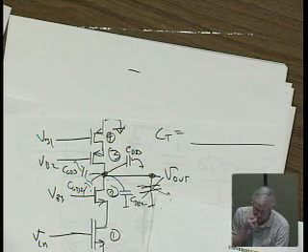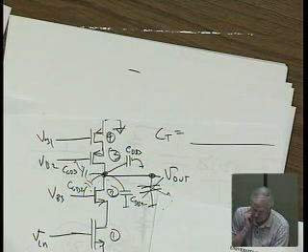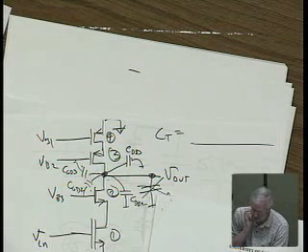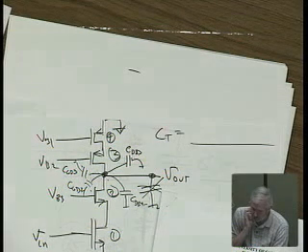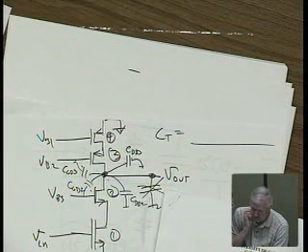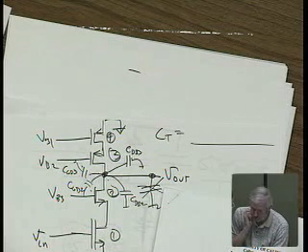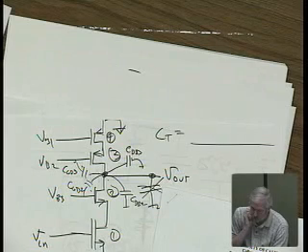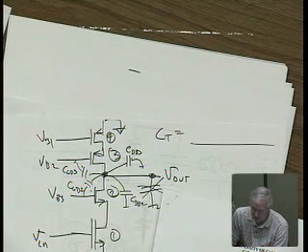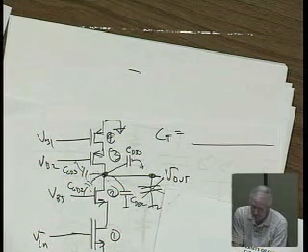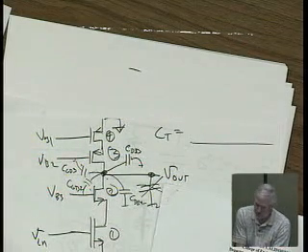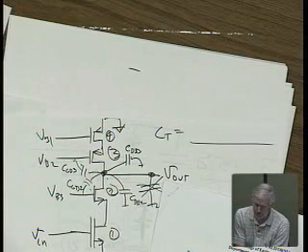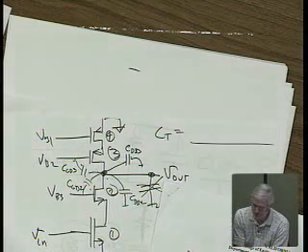For the case where I don't have any C load here, I simulated the circuit and got a pretty close value for my calculation to the simulation, but it's just for this code without CL. I got about 100 mega, but the simulation comes to 800 mega. The lowest pole is here, and the second pole here without the zero. You got 100 versus 800. What happened? Is there anything you should consider in the simulation?